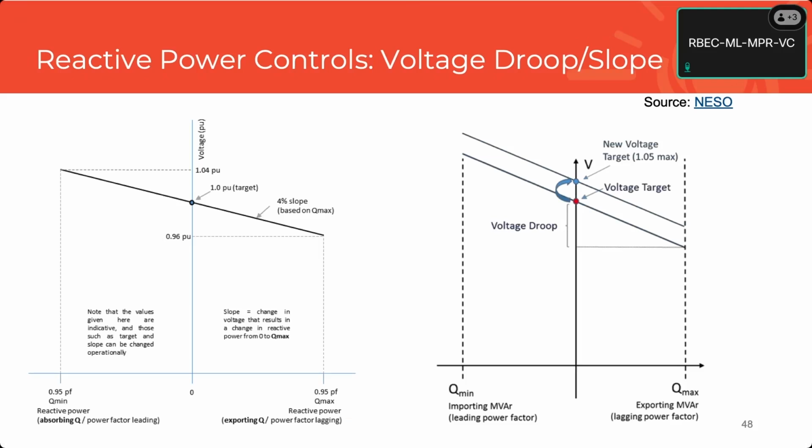Okay, that's what they're measuring. So if the Droops are flat like that, one of them will go all the way to reactive power to try and get the voltage down. And the other one, if the voltage is in between those 2 set points, will go all the way to the other side. And then if they're both actually measuring the same point, and they both have a flat Droop, there's now no one operating point.